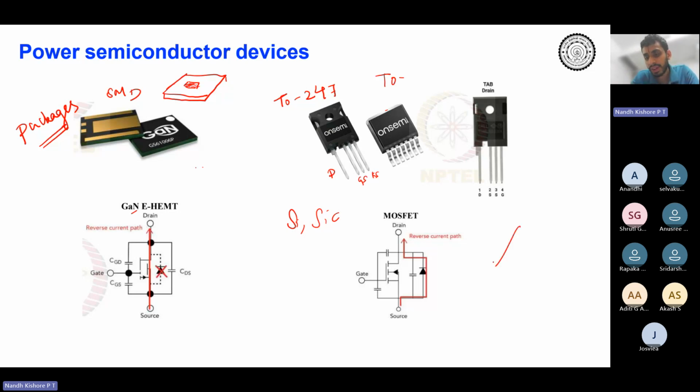Whereas these kinds of devices will go into the PCB. Let's say you imagine in 3D, then you will be having 3 holes or 4 holes on the PCB. So all these 4 terminals will go into the PCB. They will protrude from the backside of the PCB as well. So these are known as through hole devices, and this is a surface mounted device.